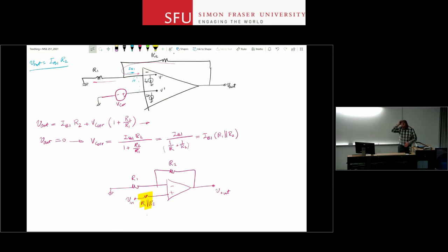Now, we talked about the saturation of the voltage at the output, so this is another non-ideality. An ideal op-amp should be able to give you any voltage at its output. A real op-amp is limited to the power supplies that you have, right? So if it is a dual supply op-amp, plus and minus 5 volt, your output voltage cannot go above plus and minus 5. From things that you learned in transistor sections, you know that if you use a BJT at the output stage, the minimum voltage you can have is one saturation voltage for that transistor above the power supply. If you have an emitter resistor, that's actually even worse. So you really can't even get to the power supply voltages, right?